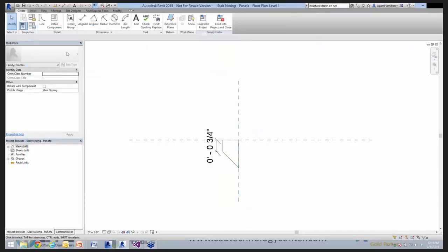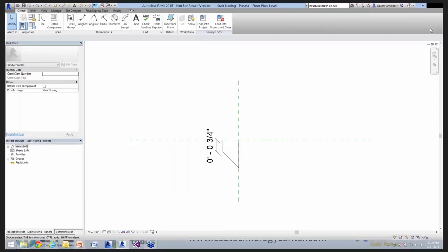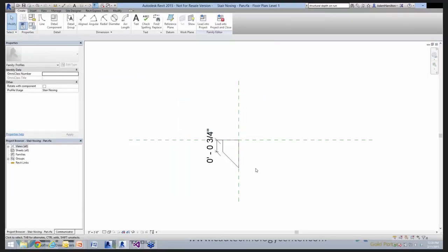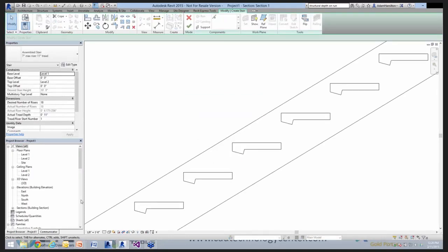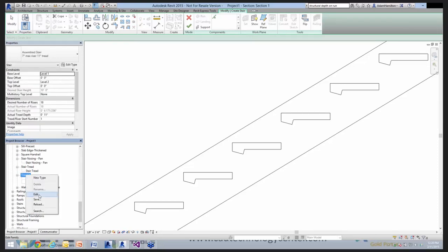And again, I always recommend save as before reloading them back in, so you can add parameters to them that can then be edited back inside the project. So editing the default families or creating a new parameter yourself is a good skill to learn.